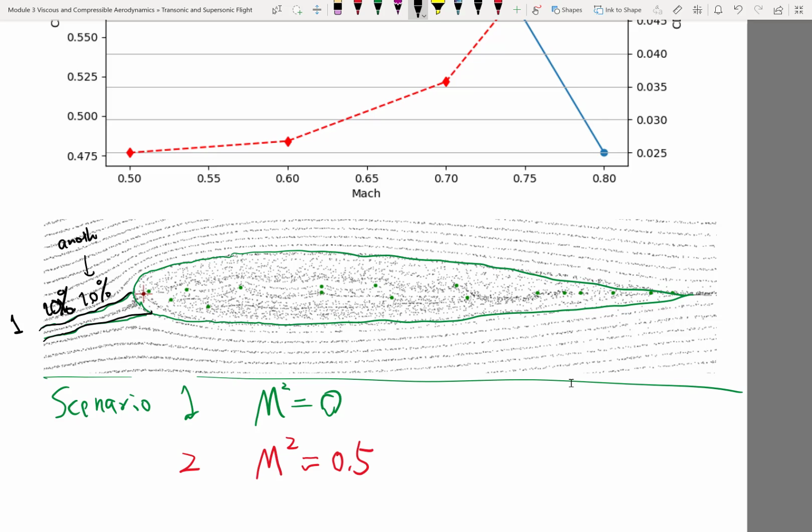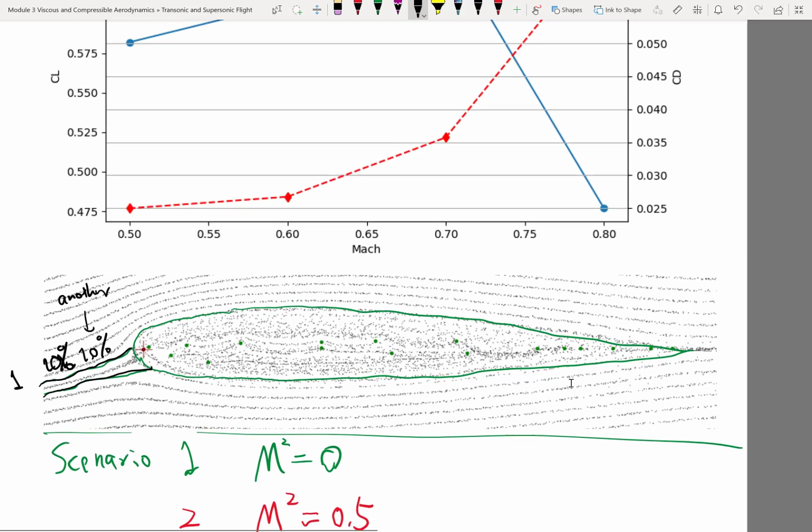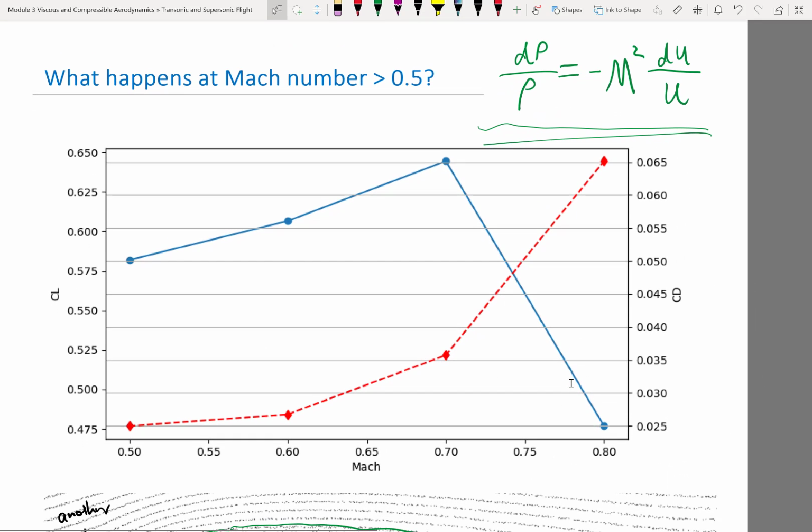Let's work out how much the velocity has changed on these two subsequent area expansions, and also how much the pressure has increased. Let's approximate the 10% increases as if they are infinitesimal, and use fractional sensitivities to work that out.